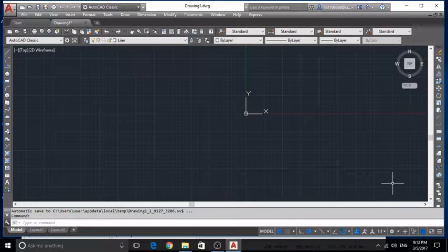I'm a student in King Saud University, College of Architecture and Planning, and today we are going to learn how to insert a PDF project into AutoCAD 2017, scale the project, and then later on, plot the project in both meters or millimeters. You will need an existing PDF file drawing ready to use.